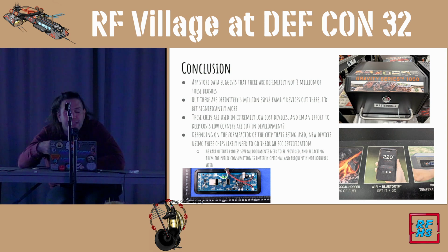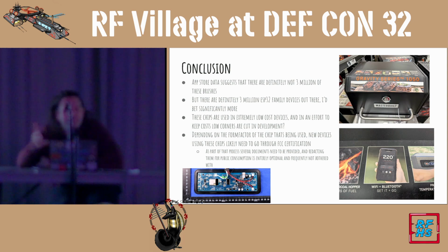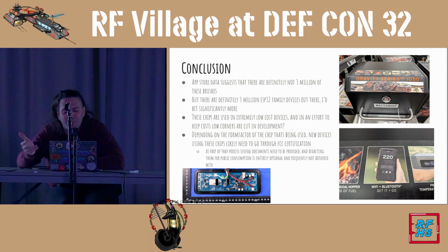and that you went ahead and used, like Evowera did, the HTTP methods to do the OTA update and didn't use the HTTPS one, which Espressif does provide one single example of, whereby you've got to do a whole bunch of stuff where you hard code your own cert within your own sketch. And so my suspicion is that essentially any product that has an ESP32 in it is probably vulnerable to something along the lines of what you saw here.